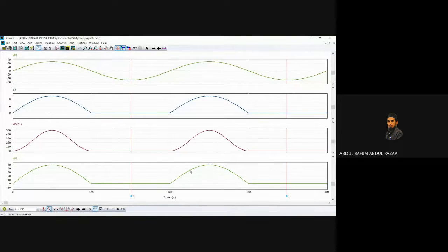The same goes for when we want to measure the actual system and its efficiency. We have to measure P in versus P out. P in is measured by measuring the current and voltage, and also P out, voltage and current. So by right, we have to have an ammeter and voltmeter on both sides.